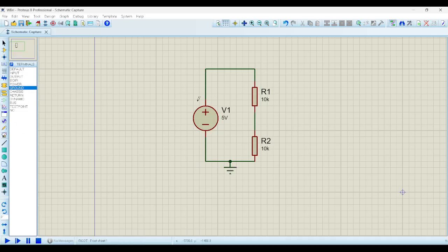and that's my circuit. So we already know that this configuration is a voltage divider, right? We have two resistors in series, and these two elements are connected in parallel with a power supply. That's a voltage divider, right? I have here one voltage, and I am going to generate another one here that is a fraction of this one. In order to measure, I will add a voltage probe in here between the two resistors.